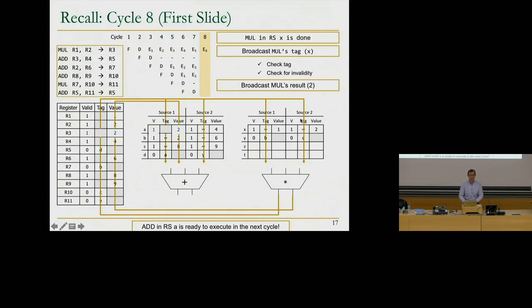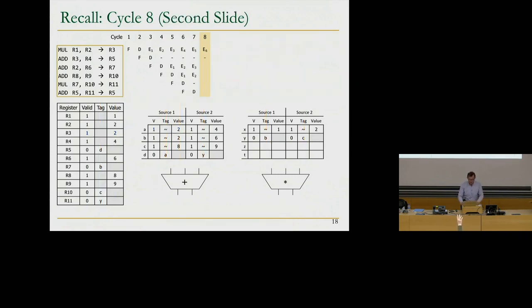So if you want to have lots of instructions, lots of reservation stations, the cost of this increases. And also, you need to broadcast the value, so you need to have buses when you broadcast the value. If the tag matches, and if this is not valid, you capture the value and write the result in the appropriate location, just like we did over here. So that's also cost.